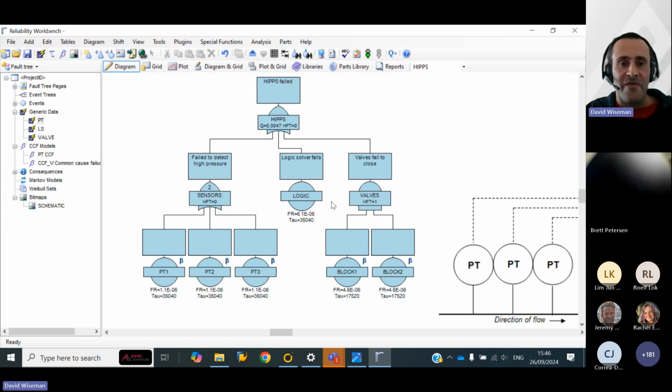You'll notice also that for each gate, the program is showing a hardware fault tolerance that is based on your SIL target, the safe failure fractions of the individual events, and of course, the type of failure. Is it well understood or is it not so well understood?